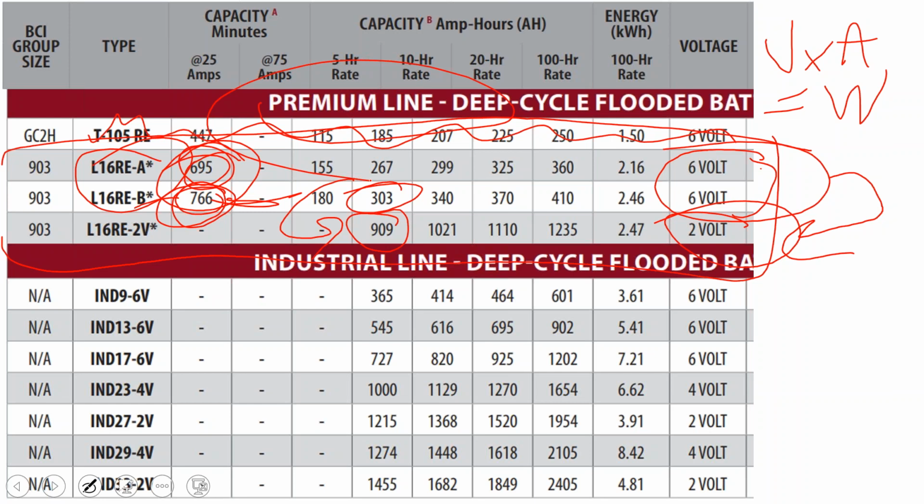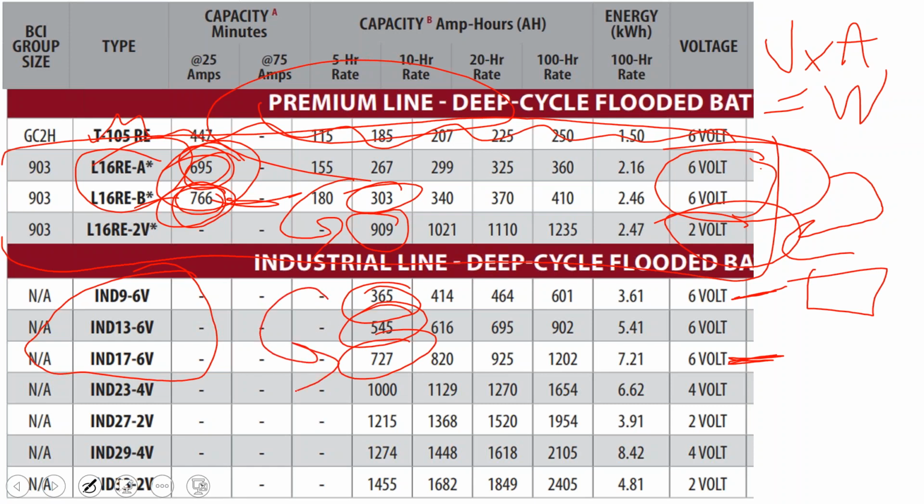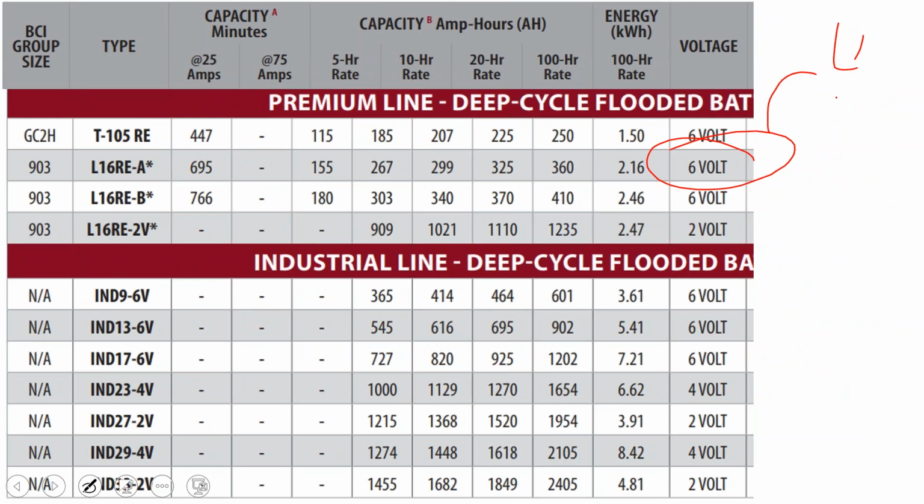Now we get into other product lines where we can see these 6-volt batteries where the amperage is actually increasing. Usually what this means is this battery right here may weigh 100 pounds and only be 1 foot tall, just making up some numbers here. Whereas this battery may weigh effectively 2.5 times as much and effectively just be 2.5 times taller. So when you're buying a more powerful battery of the same battery chemistry, the more powerful your battery, the larger and heavier it can be. And so the one issue is, all else being equal, if we're going up to 48 volts, do we go with a 6-volt battery or do we go with a 2-volt battery?